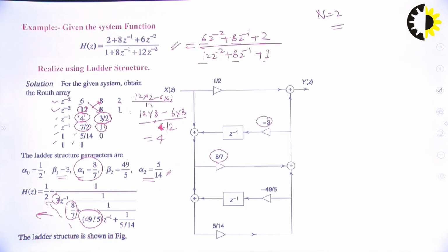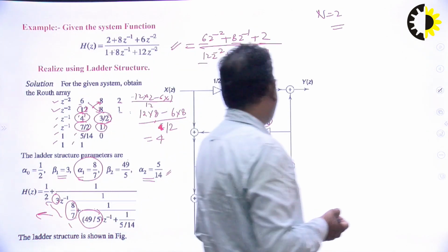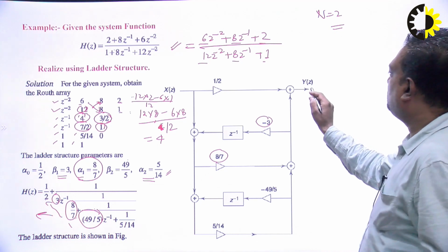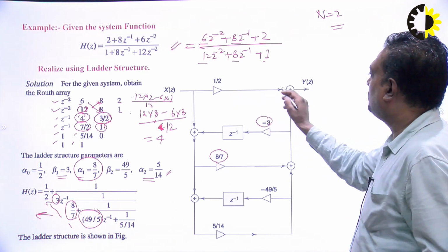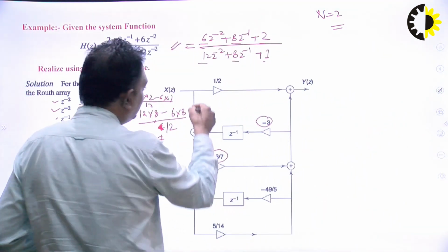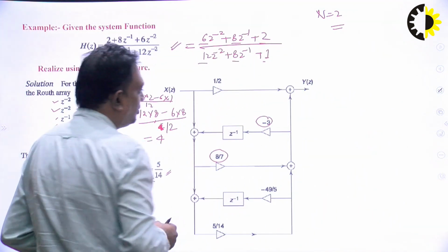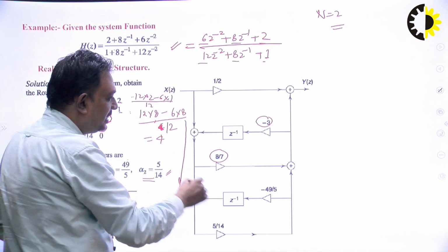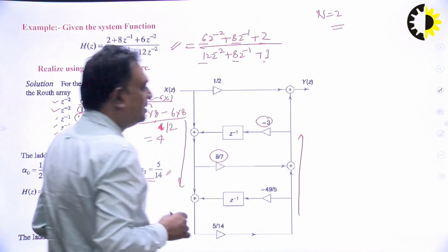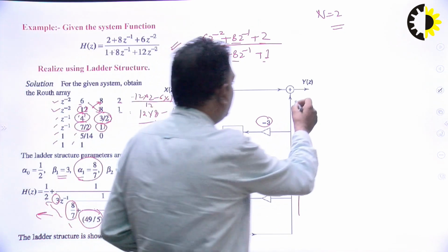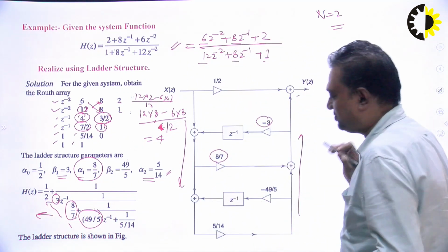Now the important thing is where we have to put the adders. Adders are always there where two signals are added. So if you are getting some output over here, input comes over here and input comes over here. And in this adder, input comes in this direction. You can see your signal flow direction is from here to here and from here to here. So it is important that you alternately put the adders here, here, here, here, like this.